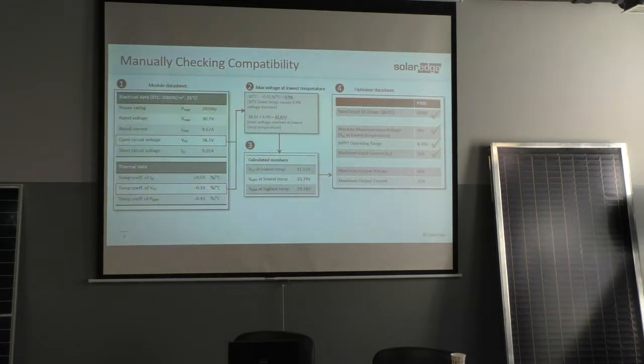Okay, it's important to know that many values in data sheets are taken from the standard test condition of the module. But maximum voltage has to be calculated according to the minimum temperature in the region where you are working.